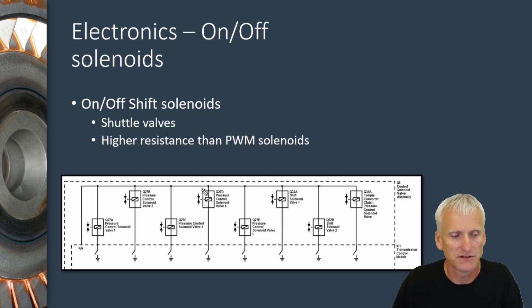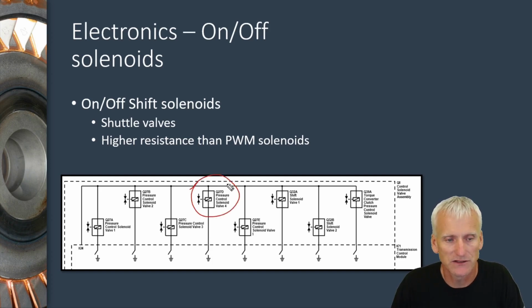And sometimes they'll actually see where they measure current flow through, especially these pulse width modulated solenoids. Sometimes they'll monitor current flow through it. When they monitor current flow, you can see an actual and desired amperage right there on the scan tool, and that's beneficial. Usually when you see that though, you don't have just 12 volts feeding a bunch of solenoids.